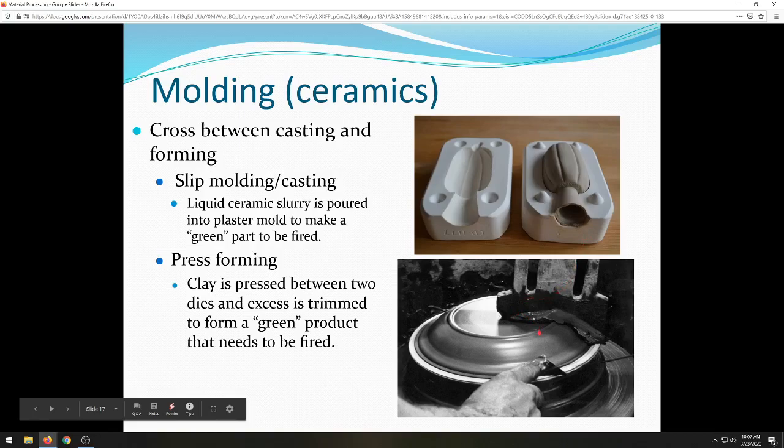This arm creates this shape, and you can see it kind of cuts the clay a little bit as the clay spins. But mainly, it's just pressing the clay up against this underside mold here, and then the worker has a little trimming tool, so you can actually see this little bit being trimmed off here as it's spinning. Because it's such a motion-intensive process, it's actually really hard to find a good image. But basically, the clay just gets squeezed between two pieces.